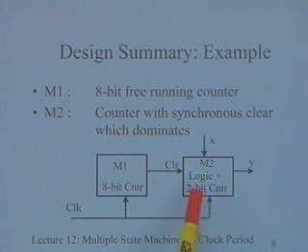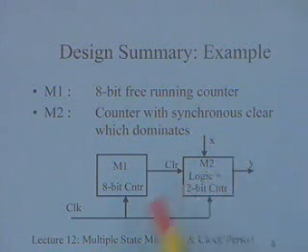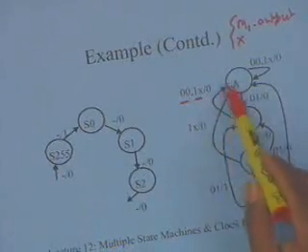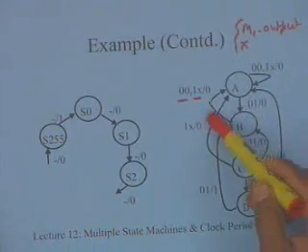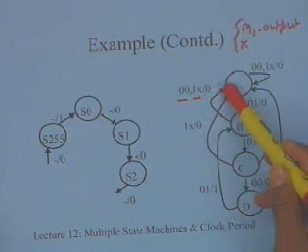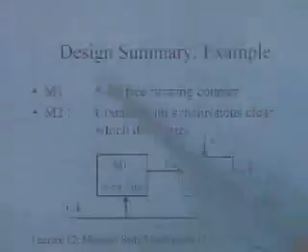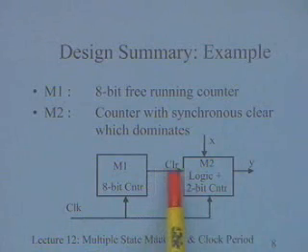If for the rest of your synthesis you also need to use this clear input, you can OR that. If there are other conditions also you would like to clear, for example, there are situations where even with a 0 you are coming back over here, so you want to implement this particular edge also using a clear input of the counter, you can take this condition and OR it with the condition that is there for this.